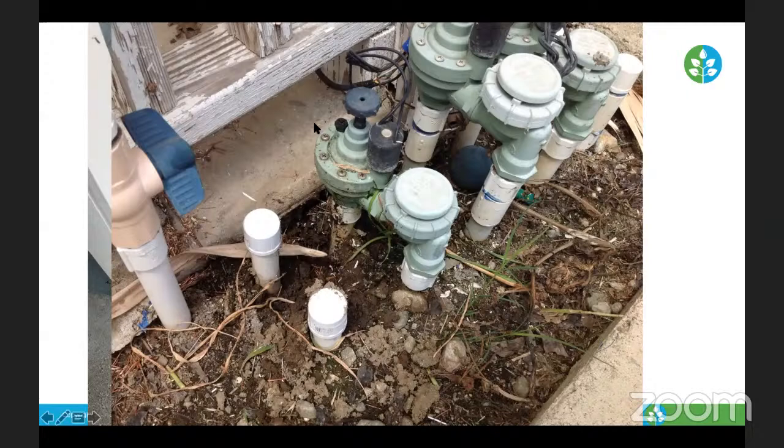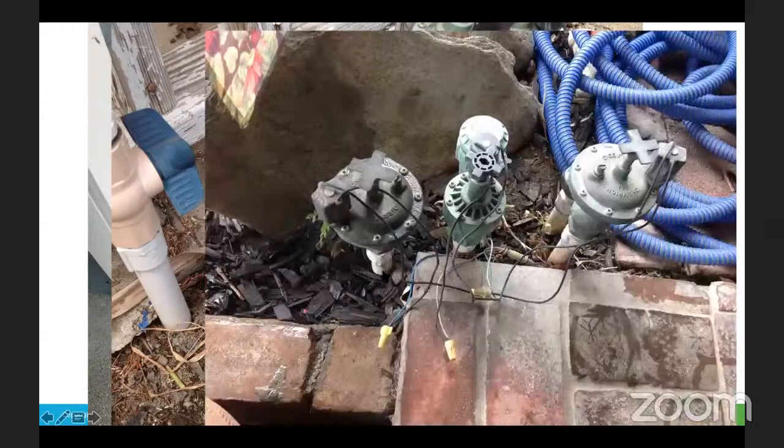So this is not the prescribed clearance for this anti-siphon component to be operating properly. So this is not up to code now. Something to think about when you do need to do a repair: you have to keep the height. Sometimes, when it comes to replacing a valve, you have to dig out the entire manifold and redo the piping down below so that you can have the proper elevation.